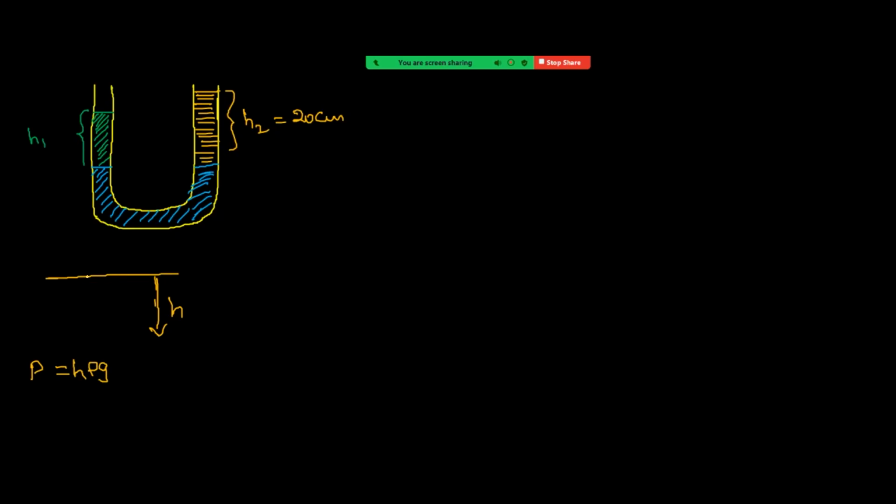In such a case, at a depth h, at each and every point, same depth, same liquid, h value same, rho value same. When free surface is horizontal, in such a case, at same depth in same liquid, pressure will be same. Okay, because g is a constant.